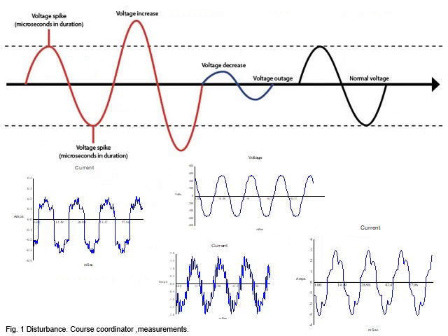See this figure. You can see here a spike built on the waveform, and this is the normal sinusoidal waveform. This is the maximum value, this is the minimum value, but we can see some spikes occurred. Or sometimes the peak increased where we have an increase in voltage, over voltage. Under voltage is when it goes down, you see here, this is the normal, it's reduced. Or cut off when we have a shutdown in the supply.